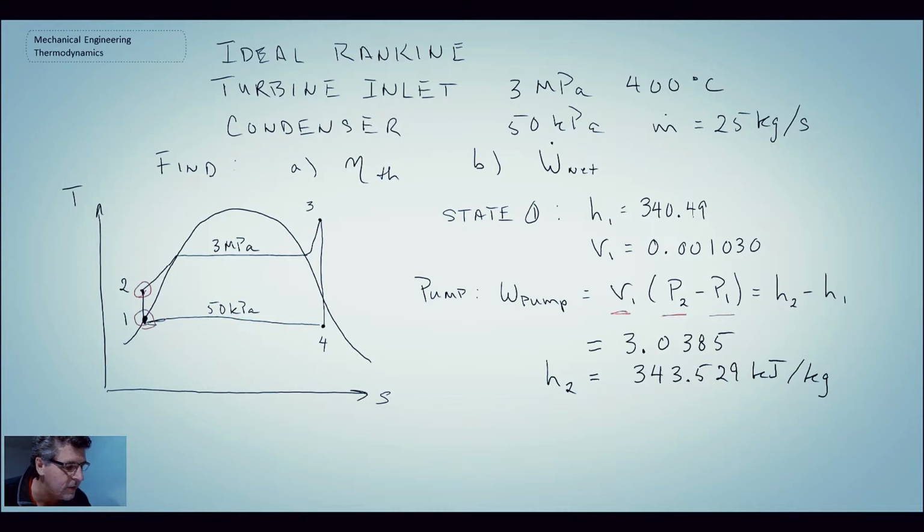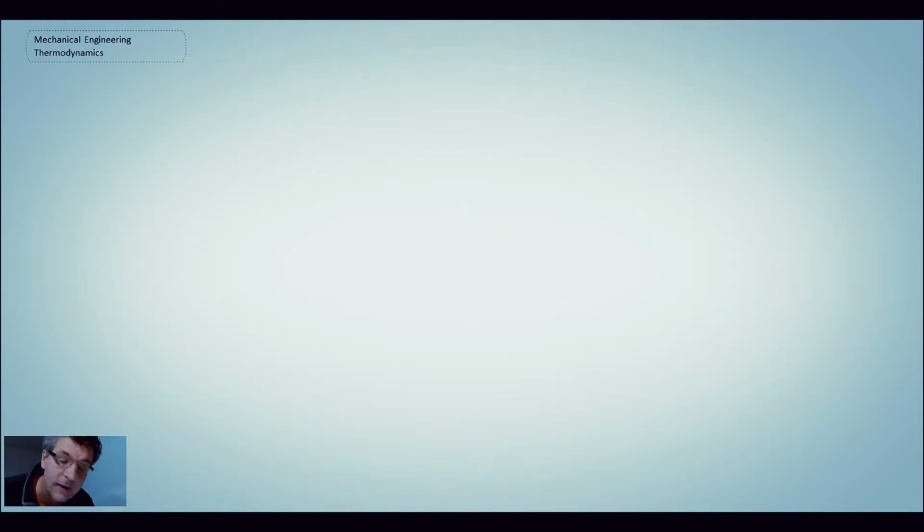In order to do that, what we have to do first of all is determine, are we superheated? So you go and you look at 3 megapascals and 400 degrees C. Are you in a saturated region or are you superheated? And for this case, it'll be superheated. So that takes us to state 3.